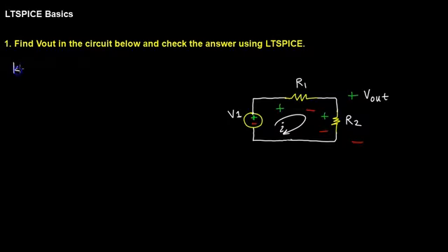Using KVL, we can find negative V1 plus, the current's looping through plus to minus, so that's positive according to passive sign convention, I times R1. Again, it's going to go clockwise and see the positive sign first, so I R2 is my next term. And then I'm going to set that to 0 because it's KVL. The sum of all the voltage rises and drops should equal 0.